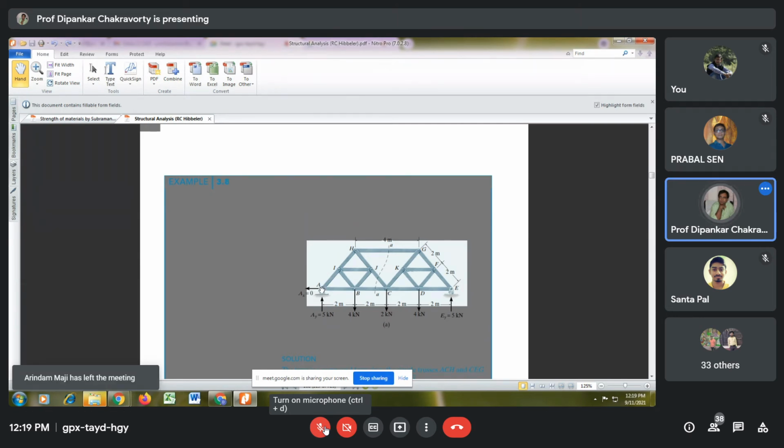In the method of joints, how many unknowns can you solve at a particular joint? Sir, 2. Yeah, two. So if you come to joint A, which members can you solve?